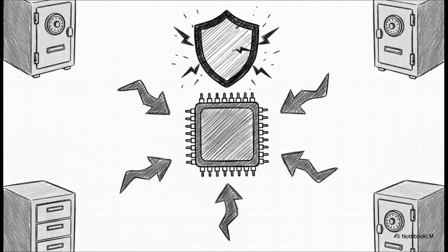This is the moment the processor steps in to save the day before your code even knows what hit it. In a sort of bullet time pacing, we see the hardware automatically taking over. It saves the address of the interrupted instruction directly into the mepc register, records the exact reason for the exception in mcause, updates the mstatus register to preserve your privilege and interrupt state, and seamlessly redirects the program counter to the trap handler address stored in mtvec.